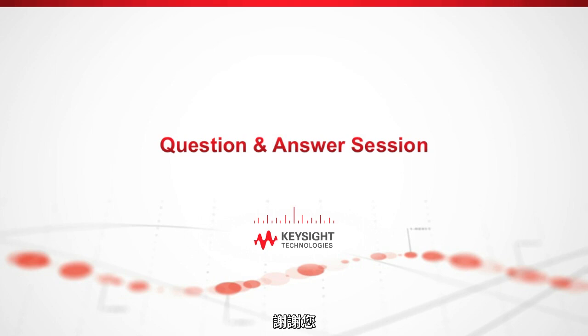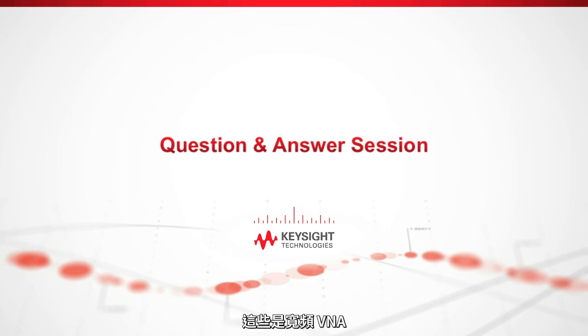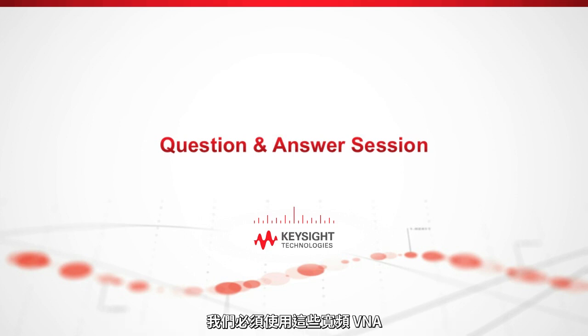Thank you. Do you have network analyzers that go above 120 gigahertz? Good question. So there are basically two types of network analyzers. There's broadband that go from very low frequencies, say 10 megahertz, all the way up to 120 gigahertz, like the one I showed you with the external modules. Those are called broadband VNAs. That's what we need for signal integrity analysis, because we have to do an IFFT, inverse fast Fourier transform, on that frequency domain data to get our time domain impedance profile. So we have to use what we refer to as broadband VNAs.